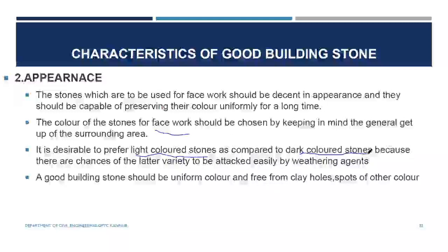This you have to keep in mind, because there are chances of the latter variety to be attacked easily by weathering agents. Latter variety means dark colored stones; there is a chance of weathering agent attack. Okay, some portion may be weathered away by some wind or some water, whatever it may be. There may be a chance of that. So better use light colored stones.